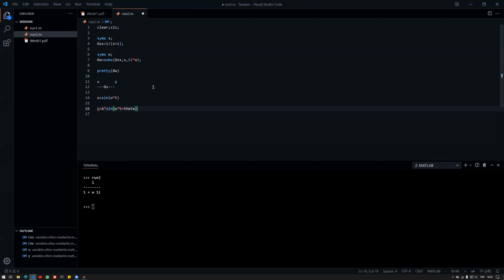So is it possible? Now, one way, and this way is basically an experimental way, is to sit in the lab, connect a signal generator, generate some sinusoidals, apply it to the system, observe the output, and look at the phase and gain differences, and prepare a plot, for example. There's another method that we can use, and which will be the case here, is to use the transfer function itself, because the data is hidden in the transfer function.